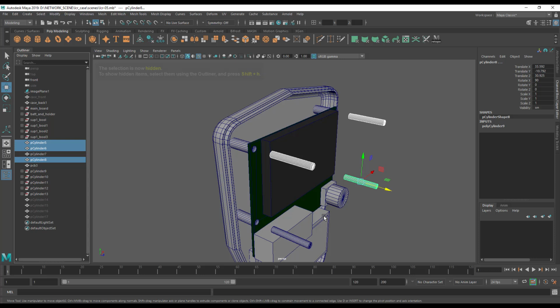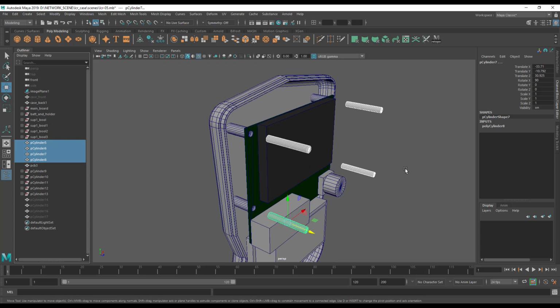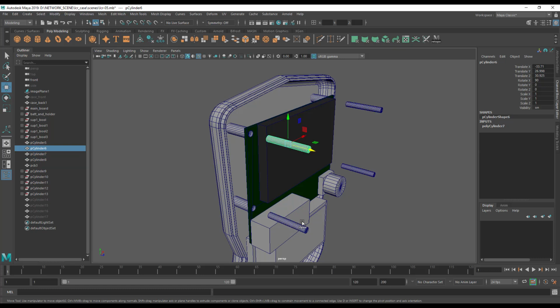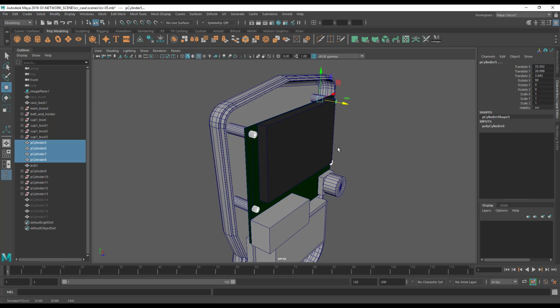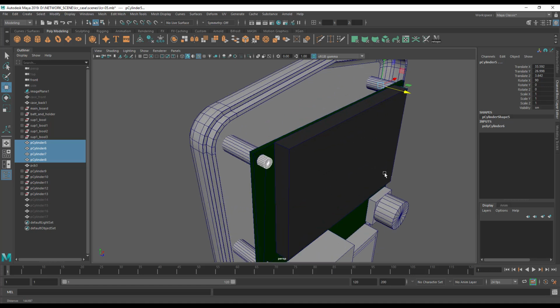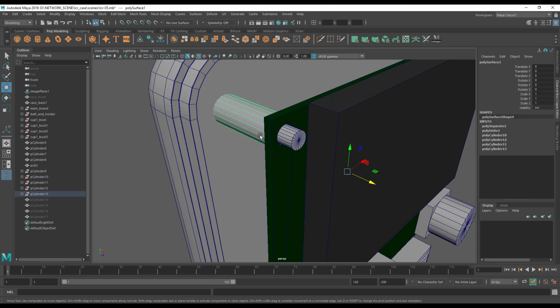Now these things should be smaller than 3mm, because we want to use screws that self-tap in, so they actually bite into the plastic. Instead of making them 3mm, we could make them say 2.8, making the radius 1.4, and we can now use these to drill holes in the support pillars. So move them backwards, make sure they completely bifurcate the support pillars, select your support pillar.